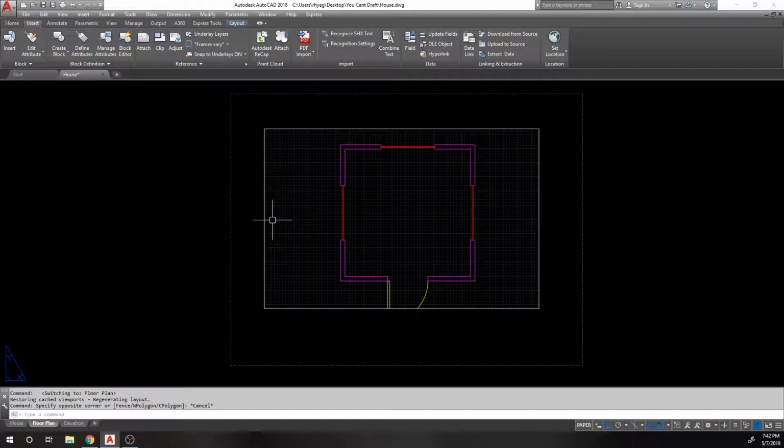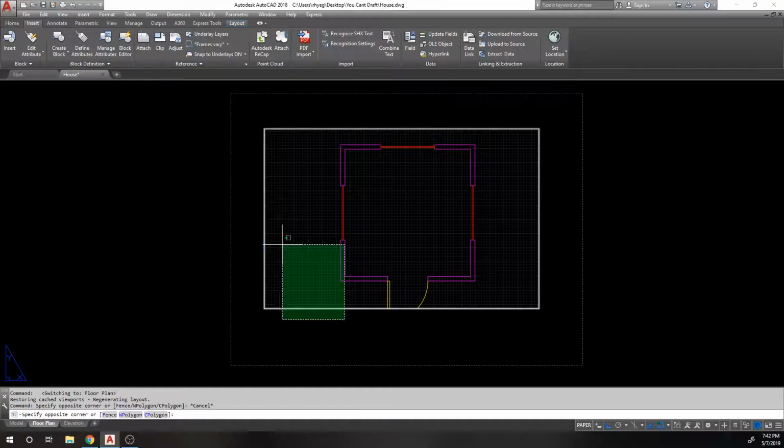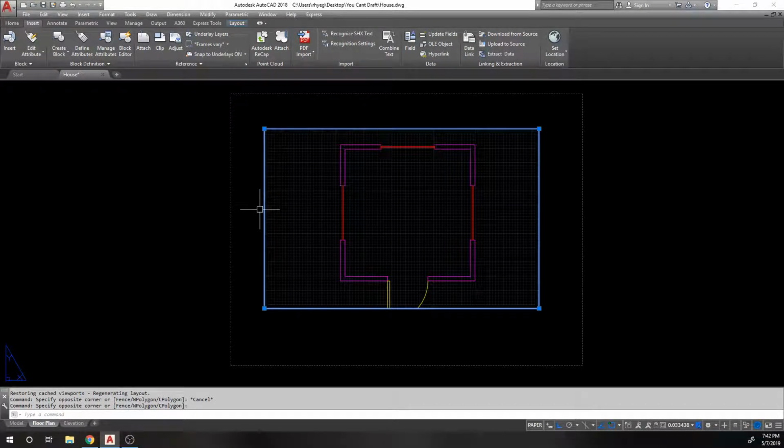Well, in a lot of industries, whenever you create drawings, you need to give those drawings a scale so that if somebody were to have a printout, they can take an architectural or engineering scale and measure out things on that drawing. So you want to have things that are printed to scale. Viewports allow you to easily print objects to scale.